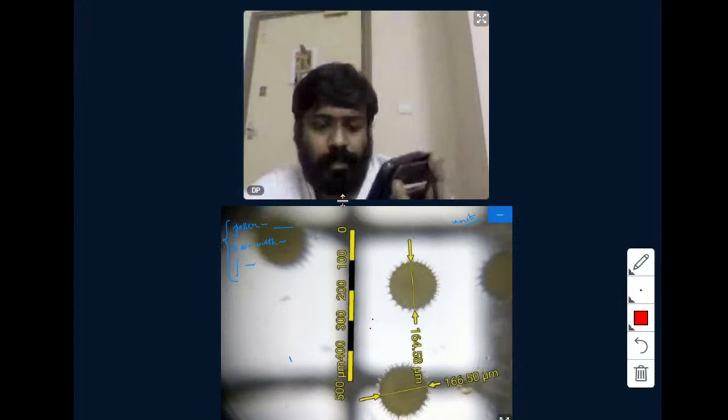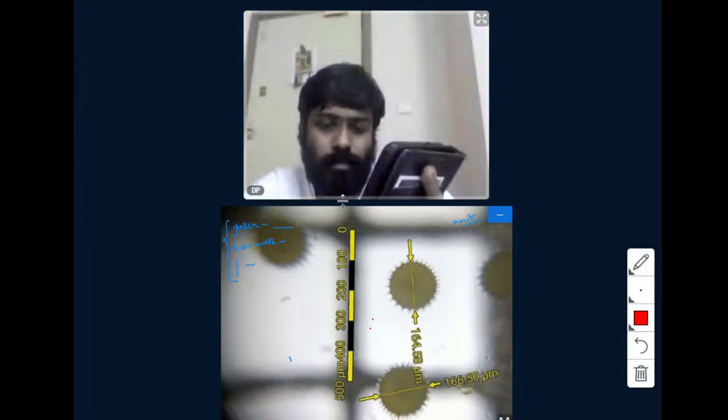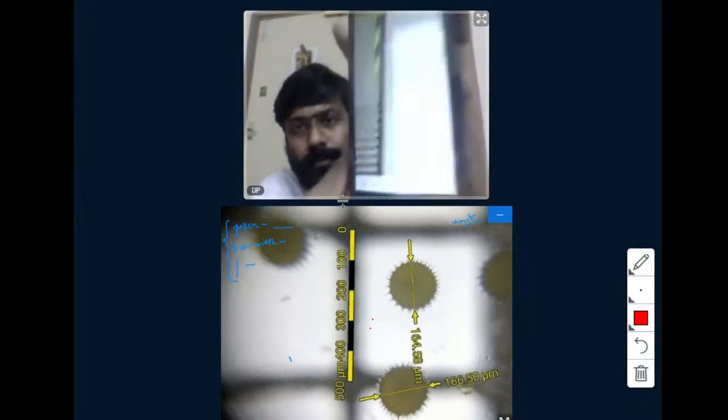Yeah, can you change the units to micrometer or something? There is an option of changing the units. So I go here. Yeah, and units. There are image settings. Scroll down, image settings, then calibrate image, then secondary label, mode on, off. In that, alternate unit.